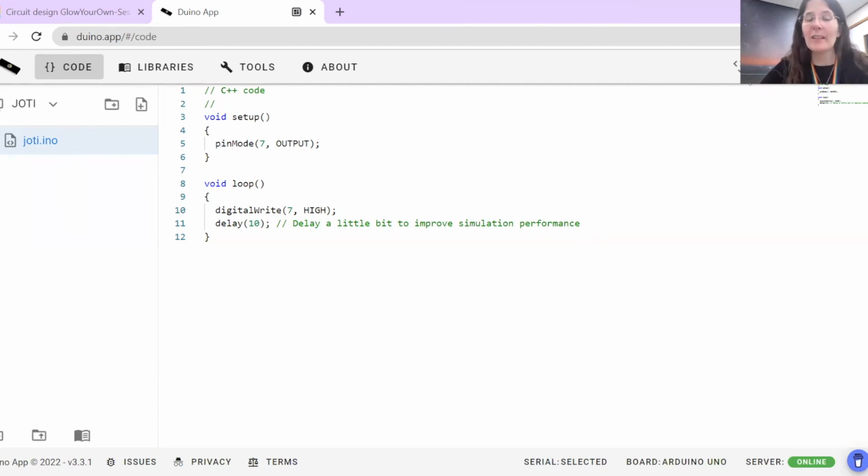Sometimes lights do turn on, but they are a little bit faint, especially with a blue LED, which is why I chose a red LED. My room is really bright, my lights are really bright, so sometimes it can be hard to see. The value of the resistor can also affect it. In the packs we get, some people may put 100 ohm ones, but they also may put a 1 kilo ohm or 10 kilo ohm one, which would make the light dim.